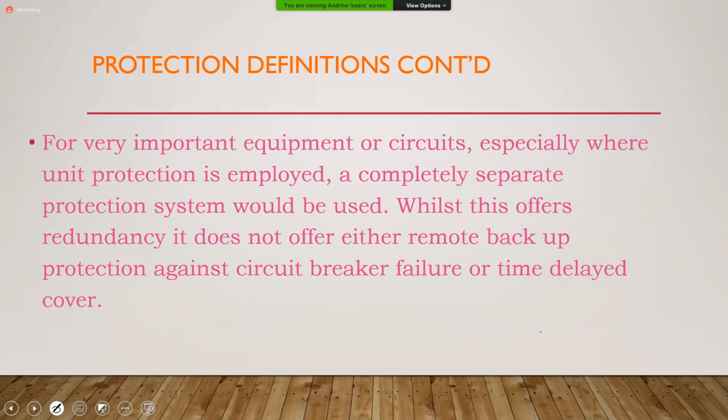What this is saying is that you really don't want to depend on some of the equipment that is used in the primary protection. Things like voltage transformers are very expensive. They can be as expensive as your power transformers, so you don't want to replicate those. But certainly you may want to use a different set of CTs, and obviously you'd use different wiring.